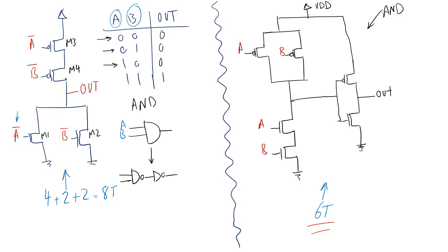Okay, so this is why back when we were talking about simple logic design, I was telling you guys that normally we built everything based on NAND, and I know that we defined the NAND gate as an AND plus an inverter, but in reality you can see that an AND is really a NAND plus an inverter. Okay, this is one of those counterintuitive things that happens in digital logic design.